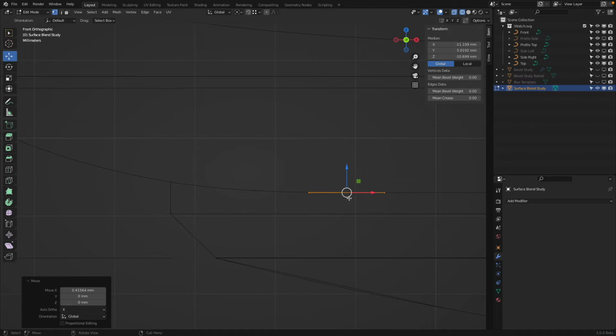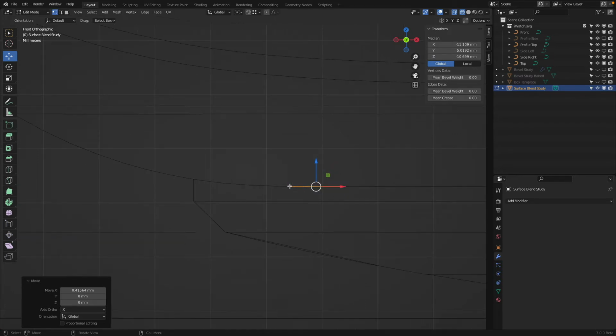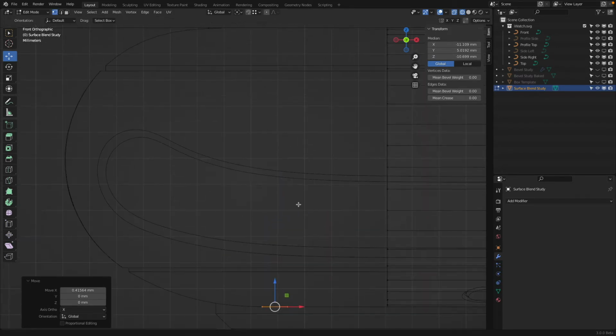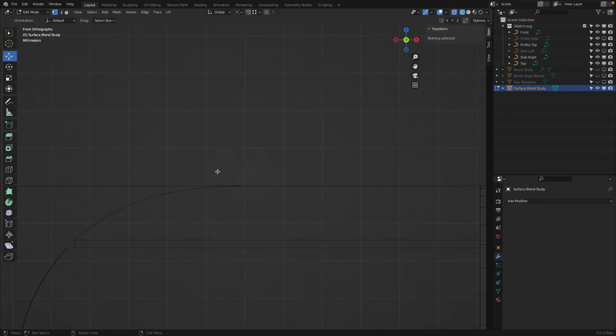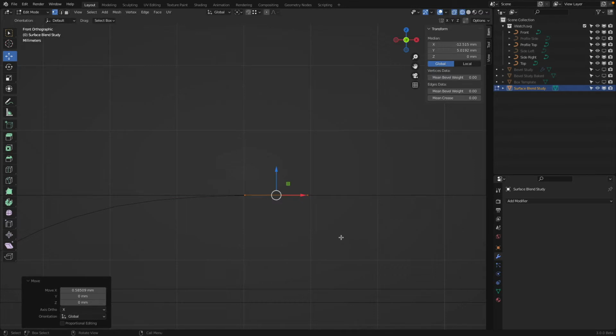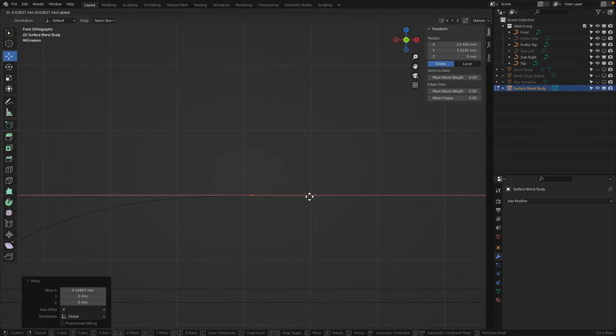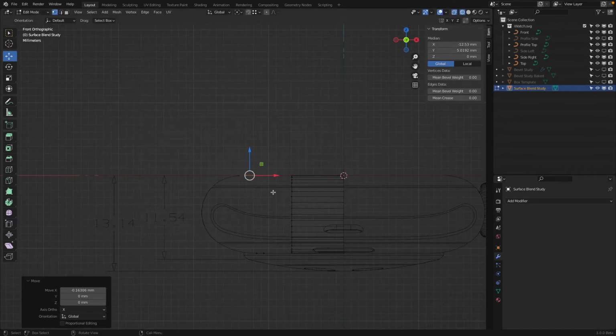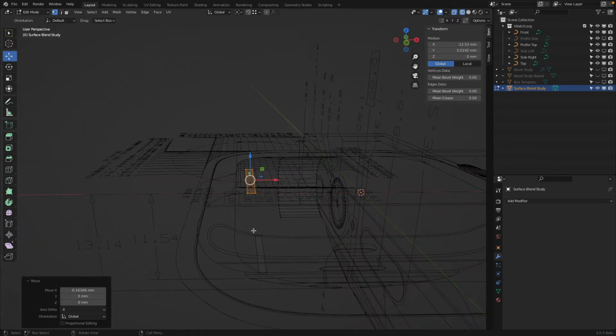Or maybe a little bit to there. You see that this point sits on this line. AA to deselect everything. We do the same here, a little bit to there. Okay, good. So here now comes the interesting part. Click, click, click, click. So these front edges, and now we will create a blend surface.